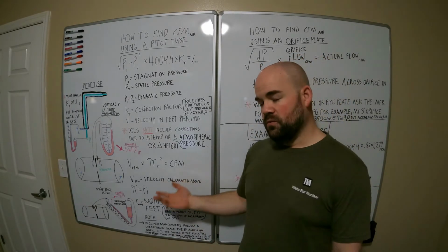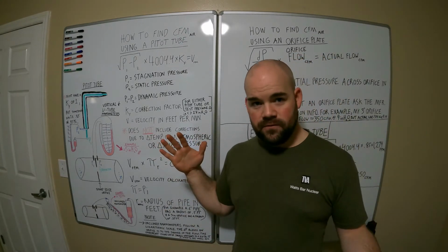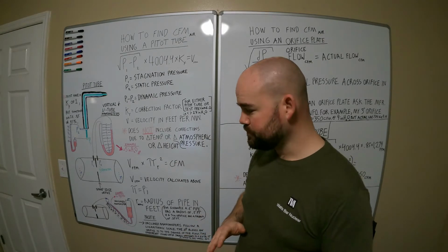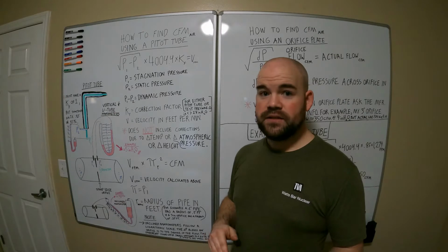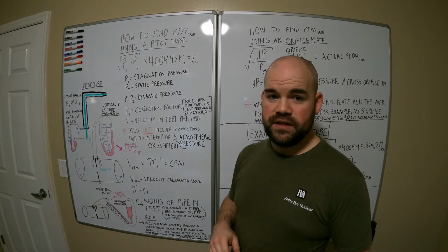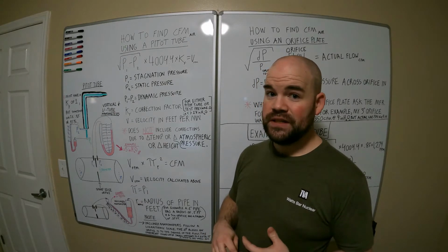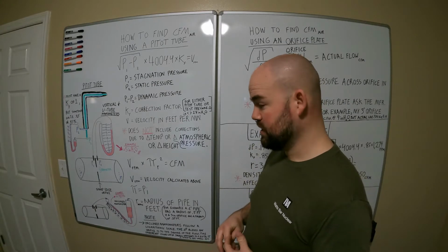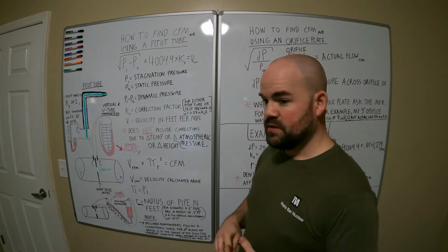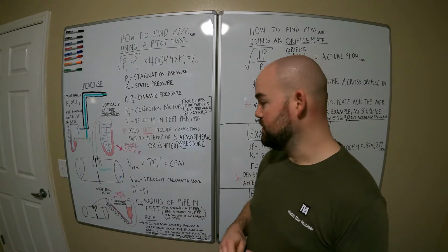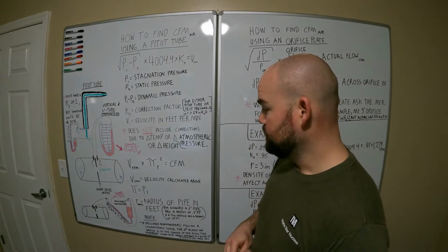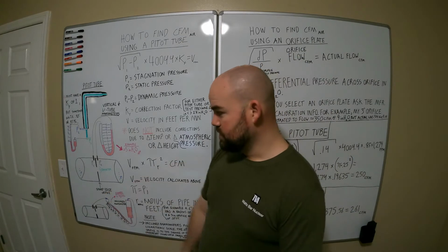Now, if you have a need for a smaller footprint and you have the budget, you can go get some of the blue gauge oil that they use in the SF600 benches, but it's like $150 for 4 ounces, so it's pretty expensive stuff. And it has a specific gravity of 1.9 something. It's almost a specific gravity of 2. But anyway, this is how you can get a percentage flow.